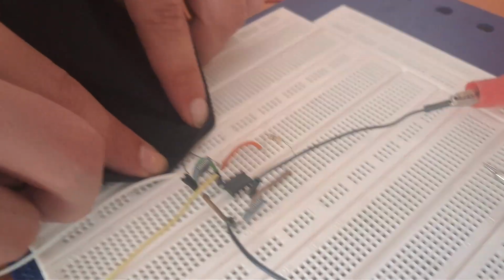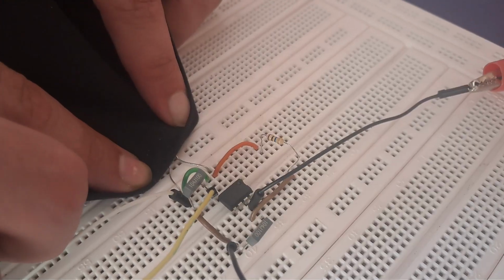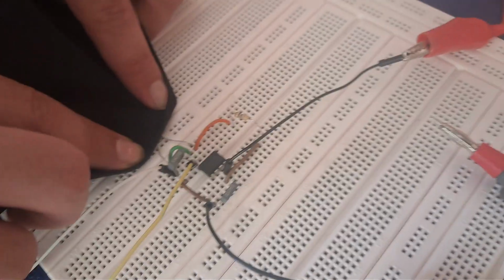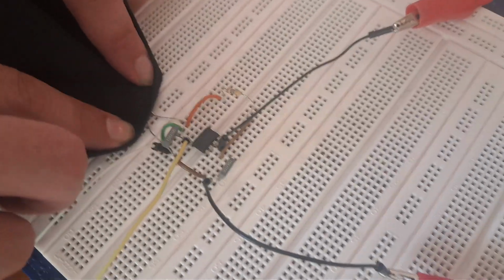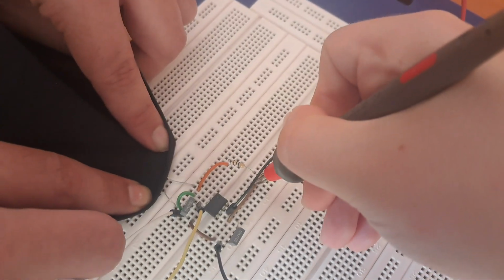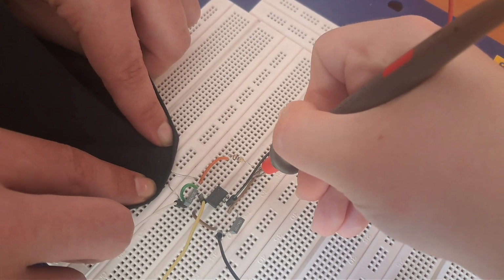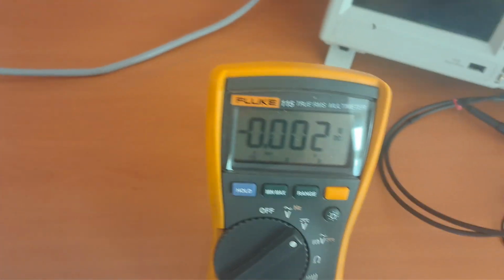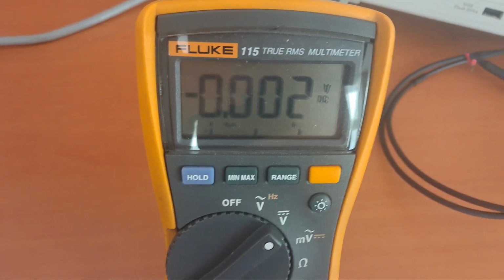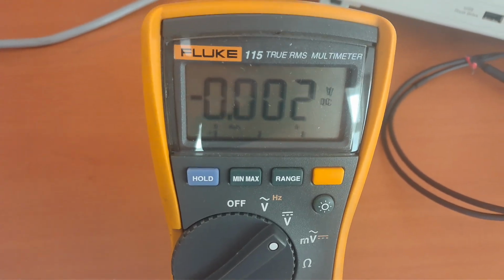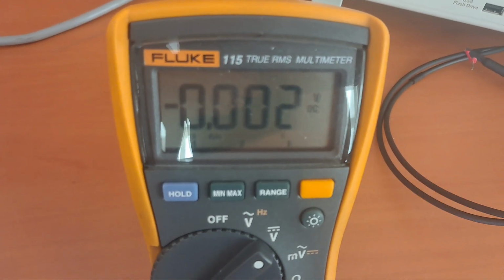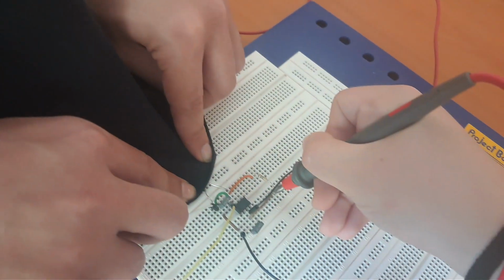For the last condition, I'm getting help from my friend. We used a black fabric to cover the photodiode, and now I'm gonna measure the output voltage again under these conditions. It gave us a negative voltage, which makes sense because there's some offset voltage. So I'm gonna divide it by the resistance and try to understand our calculations.